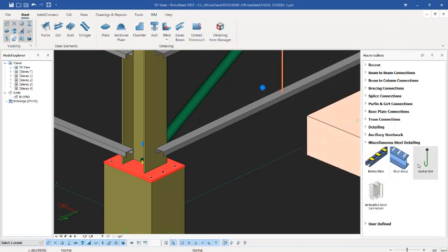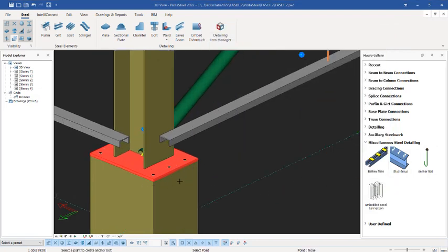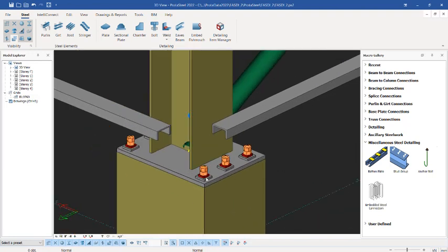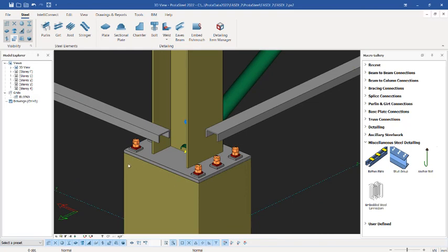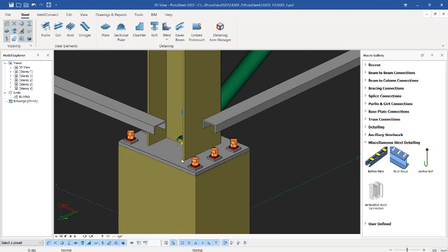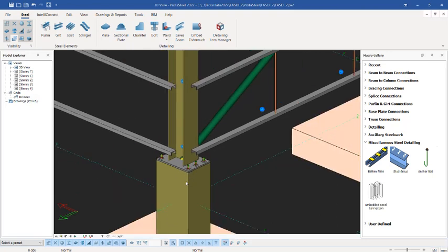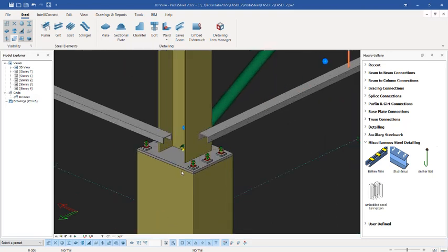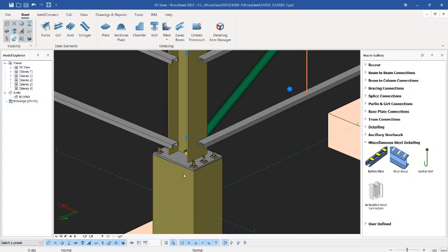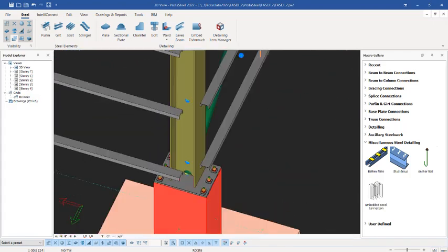After which just left click on it. Once you left click on it, you just have to right click first and then select the plate. It will locate the points automatically, and it's being fixed just the way you're seeing right now. Okay, so this has been fixed successfully. This is how you manually model and then create your base plate successfully. If you check it very well, everything is very nice and okay.